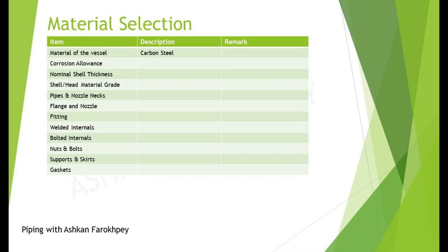As we usually use 1.6, 3 or 6 mm of corrosion allowance typically, 1.6 mm can be chosen here. In some company practices, you may find that the corrosion allowance of fixed equipment shouldn't be less than 3 mm for sour services. We respect those documents. However, in our project, we prefer to keep thickness as low as possible because we have a cryogenic service gas. You will understand more following about thickness effects on cold cracking, but generally when the thickness increases, the cracking probability goes up accordingly.